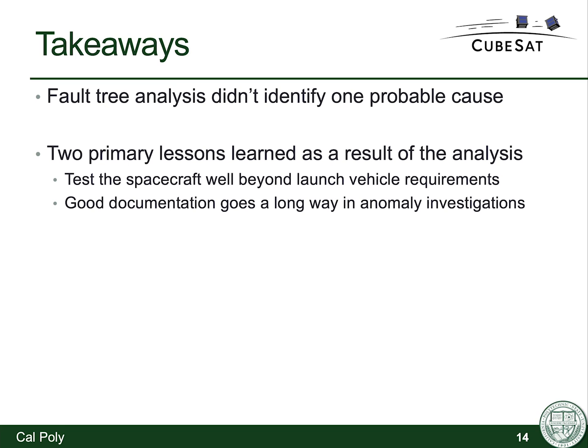The first is you always want to test your spacecraft well beyond what your launch vehicle requirements are. We did some of that with our functional TVAC testing, which identified one of our problems on the ground, but we could have done a lot more rigorous testing, especially around the battery state of charge issue that came up during the integration process, for instance.